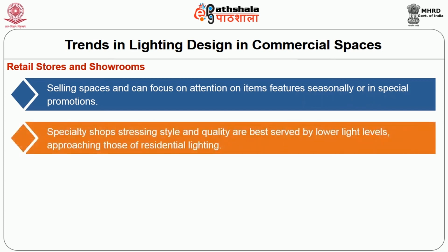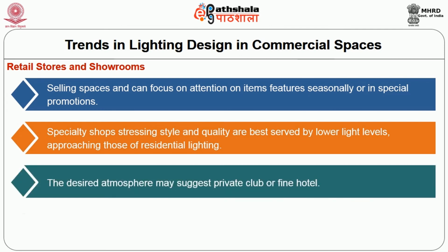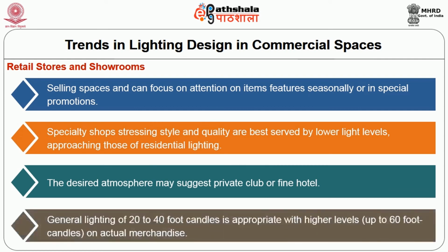Specialty shops stressing style and quality are best served by lower light levels approaching those of residential lighting. Desired atmosphere may suggest a private club or fine hotel. General lighting of 20 to 40 foot candles is appropriate, with higher levels on actual merchandise.